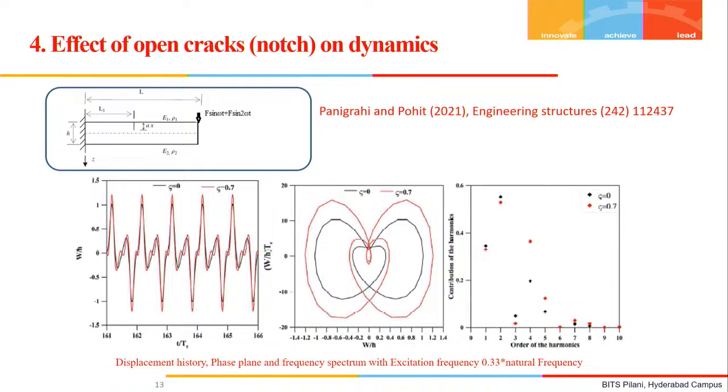This is the time displacement history, and this is a steady state response obviously, and these are the phase plane portraits. We can easily identify the cracked response compared to the intact beam response from the phase plane portrait. Interestingly, when we excite the same structure with different frequencies, the order of the harmonics changes.